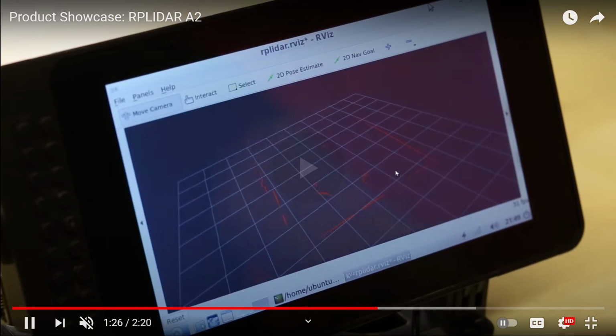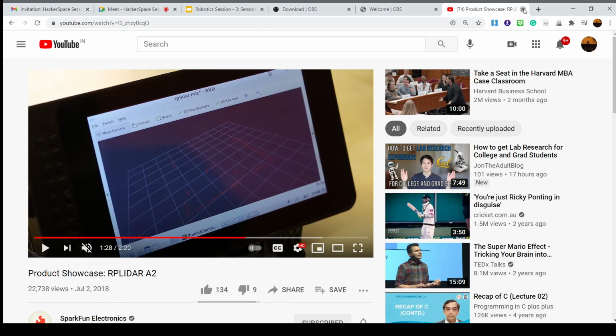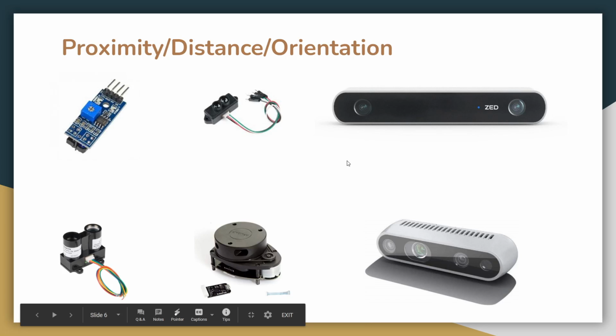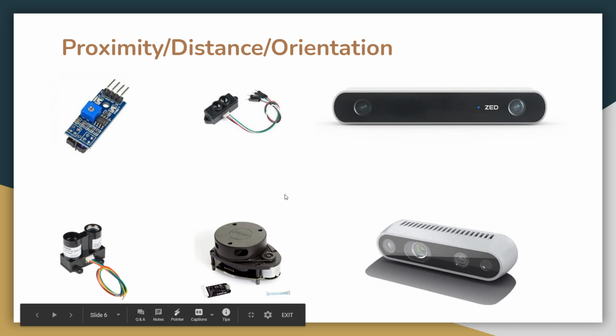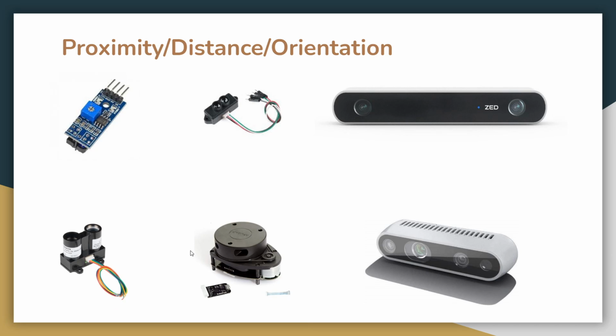And what it does while rotating is emit infrared rays once again. It's not a different electromagnetic radiation, it's the same thing, infrared. So it emits IR radiation throughout the 360 degrees field of vision, and it also has a receiver. There's a transmitter and a receiver on this as well. Due to the extremely high speed of rotation, it keeps sending IR rays in every possible direction, and then the receiver keeps receiving the rays which, after emission, hit an object or obstacle, reflect back and hit the lidar. These rays are received back by the RP lidar, and it keeps happening in an iterative loop, again and again.